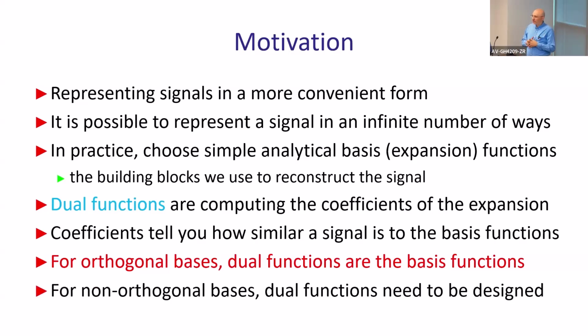And this is why, if you learn a signals and systems course, you get Fourier transforms, for example, as magic. Here is the formula, you have that exponent here, and wow, magic, to compute coefficients you have exactly the same formula, just times a coefficient, like 1 divided by T. This is the difference between computing coefficients and computing the actual Fourier transform, okay? The inverse Fourier transform is practically the same formula, just conjugate all the bases. Remember that?